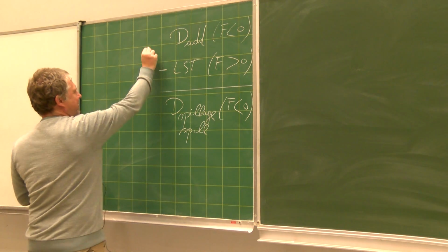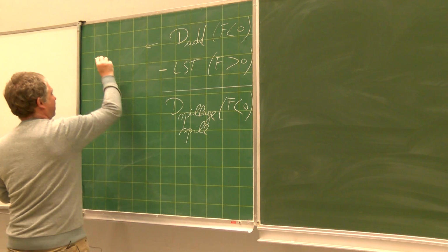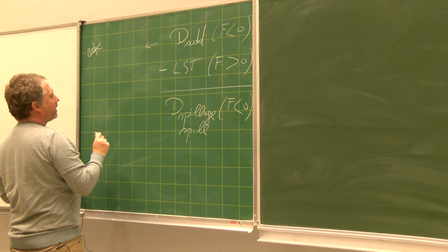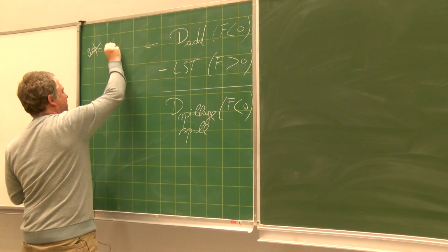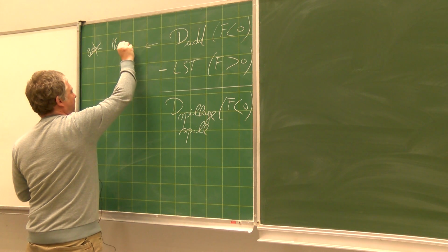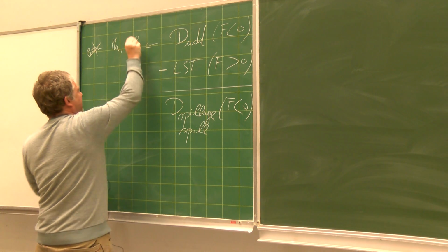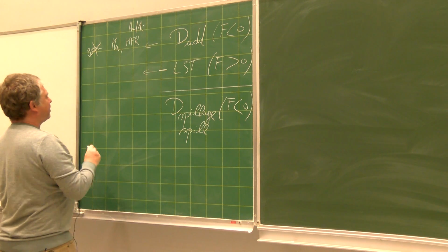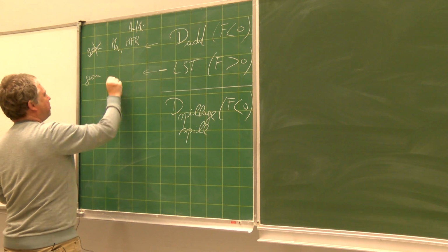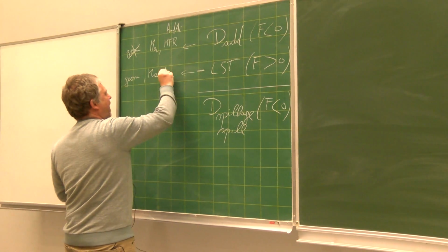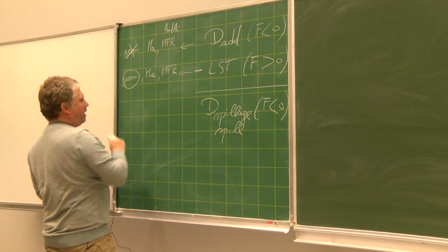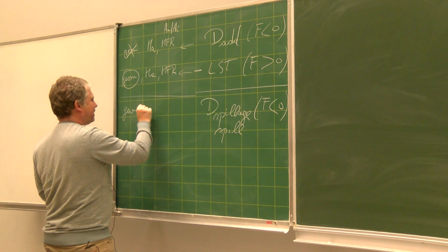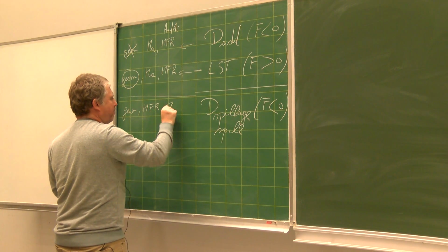And we have explained that this one is independent of the inlet geometry. It's only depending on two parameters, for example, the Mach number and also the mass flow ratio, that we have also called AA divided by AI. Whereas the lip suction thrust is a function of the geometry, of the Mach number, and of the mass flow ratio. And of course, if you make the balance, this is also a function of the geometry, the mass flow ratio, and the Mach number.